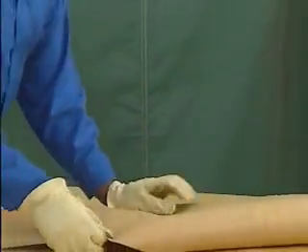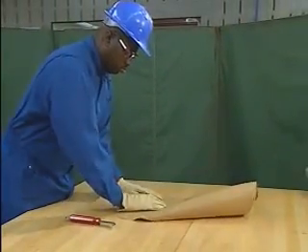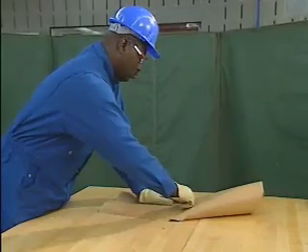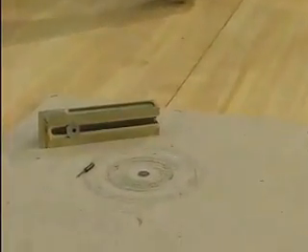Though many flat gaskets come in preformed shapes and sizes, some common replacement applications call for gaskets that are cut from sheets of gasket material. If the application calls for a circular flat gasket, one way to create the gasket is to use a gasket cutter.